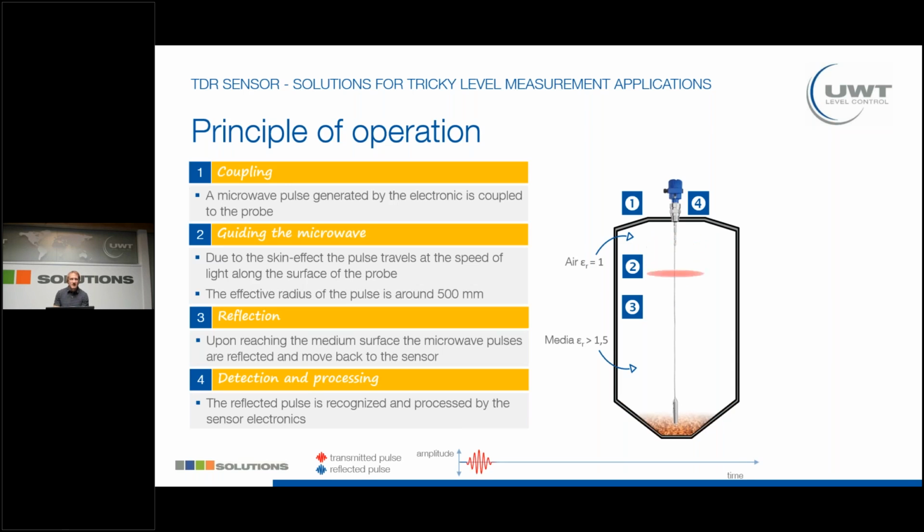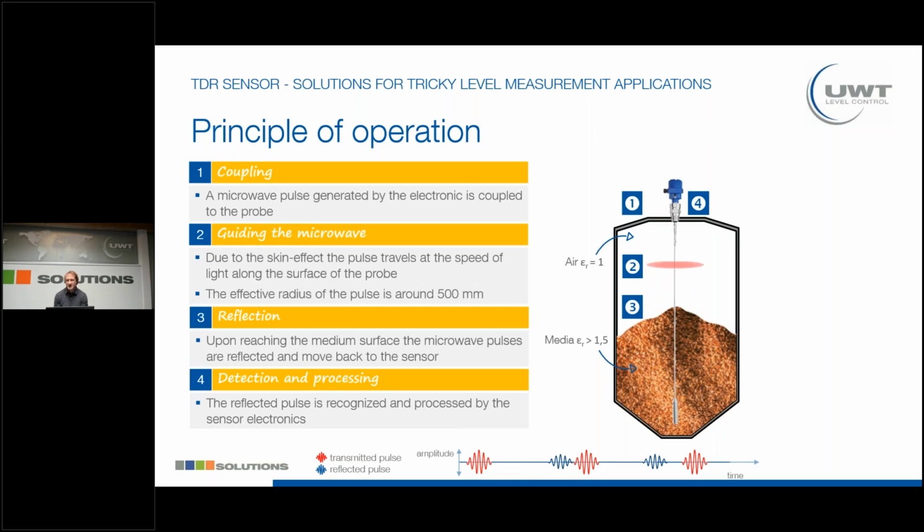So here we can see how it basically looks. So when the level reaches, the pulse gets reflected and reaches again the sensor. So the pulse to pulse time is always the same, but when the level is higher, the time difference between sent and reflected pulse is shorter.